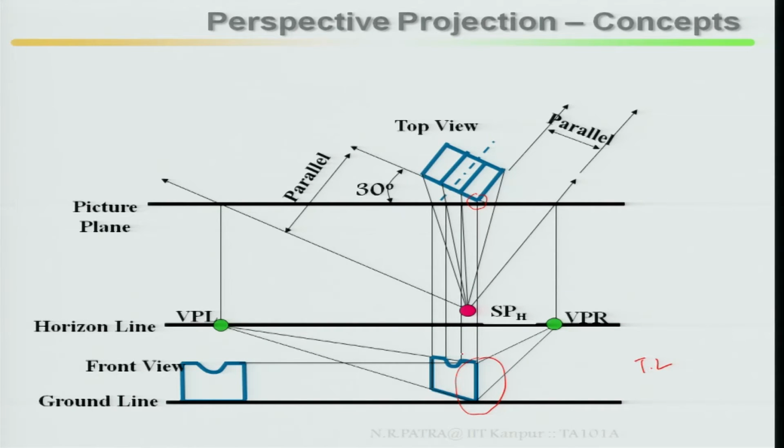then similarly go to your right hand side, identify your outer edge, this is your outer edge, then once identified, connect from the outer edge to your vanishing point left. So, it has been connected. Now, finish it. Then once that outer edge on the right hand side is finished, it is going again to the left hand side. So, whatever points you are marking have to be projected to the vanishing point towards your left hand side, connected to the outer edge of your right hand side.